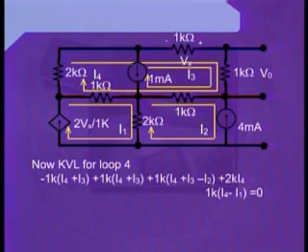Now, for this resistance, we can see that there are three currents which are flowing through this resistance. These currents are I3, which is due to the mesh 3, I4, which is due to the super mesh, and the current I2, which is due to the mesh 2, because this resistance is being shared by the three loops, that is I2, I3, and I4.